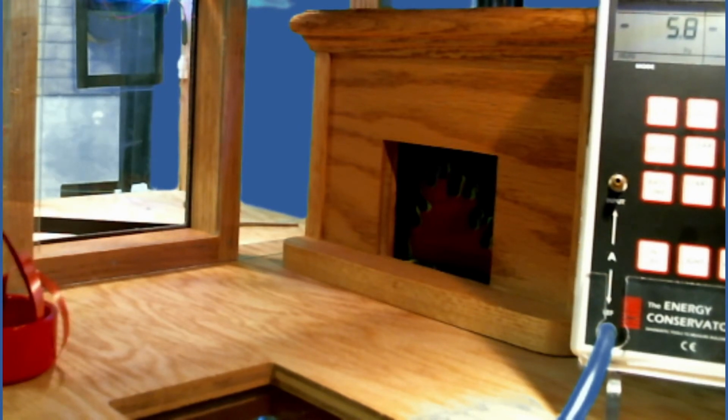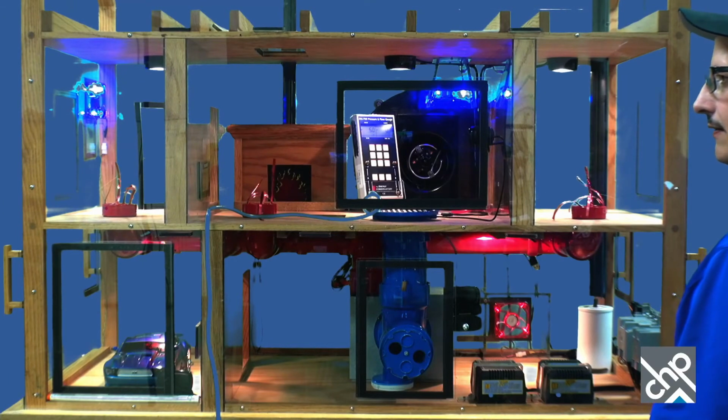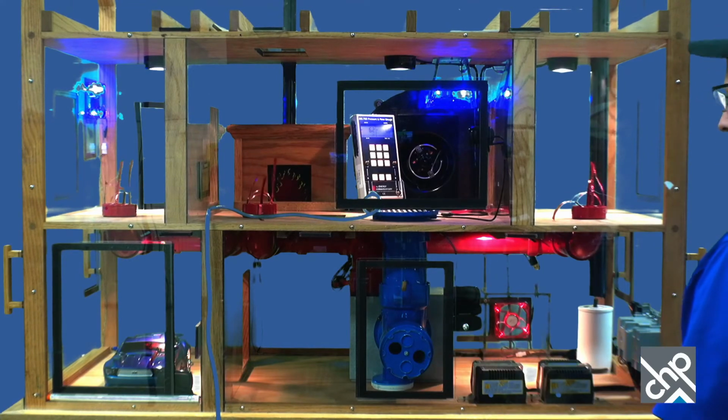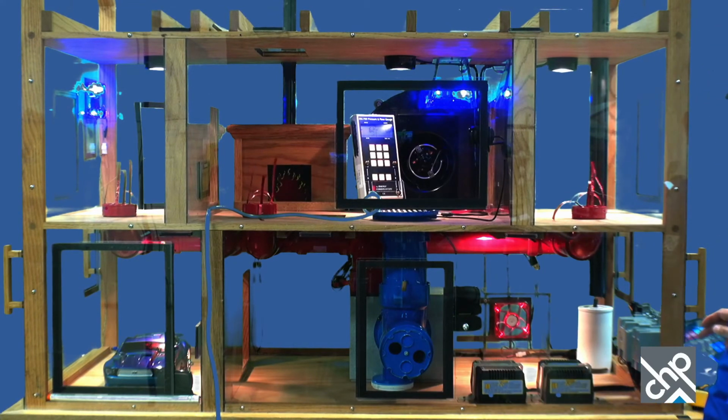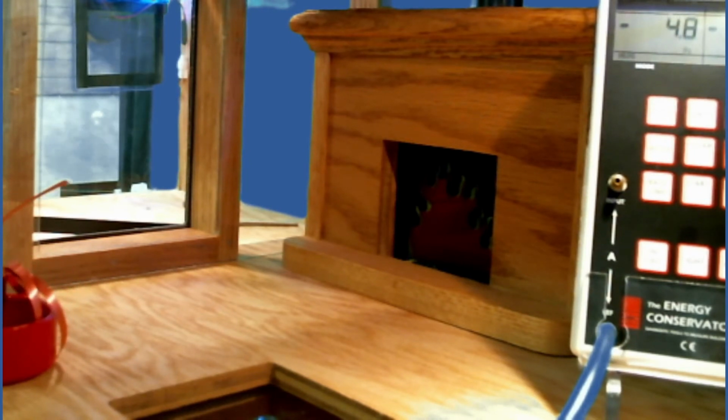So, the air handler fan, let me get back out where we can see it here. It's off, and you can see it's going to come on there. I had no duct leaks, but I do have the bedroom door closed, and we're going to check the bathroom and the basement door. So let's go back inside, and you can see there's the number. We're at 6.4 when we turn the air handler fan on. So that gives you a clue. Let's turn the air handler fan back off.